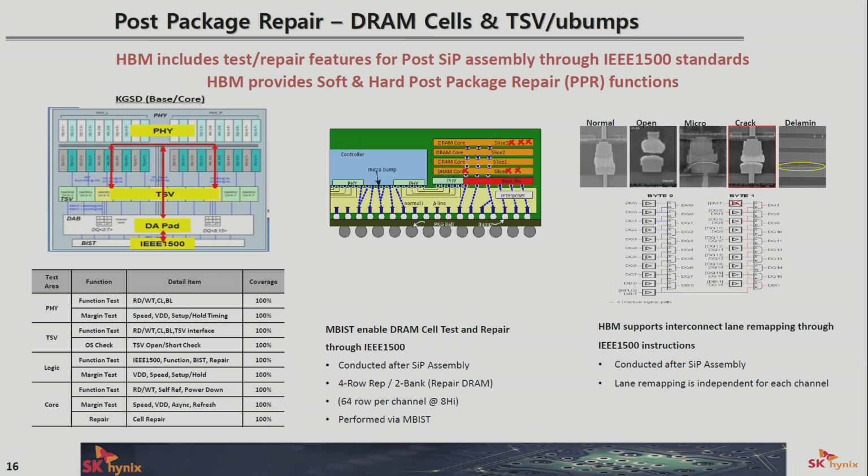And also from a DRAM cell perspective, as well as microbump or TSV, customers can use post-package repair capability. There is a hard repair function as well as soft repair that customers can do when they detect a failure at the DRAM cell or at the microbump area. I won't go into the repair mechanisms.